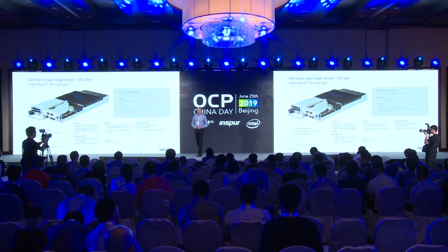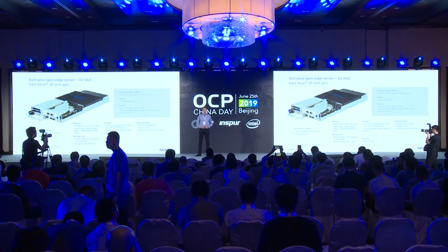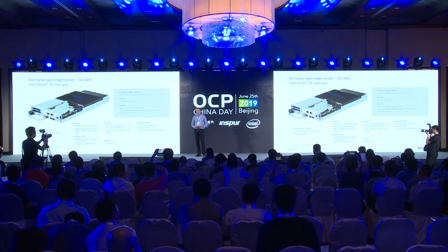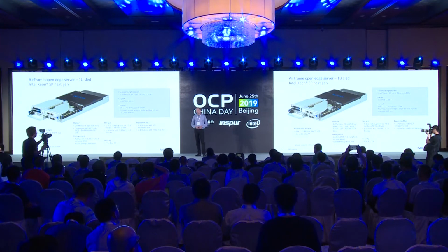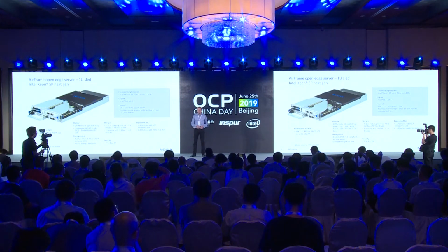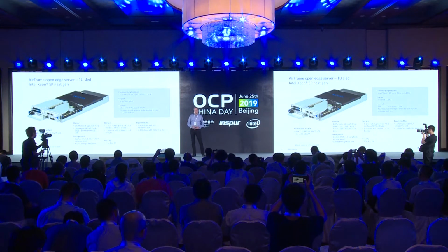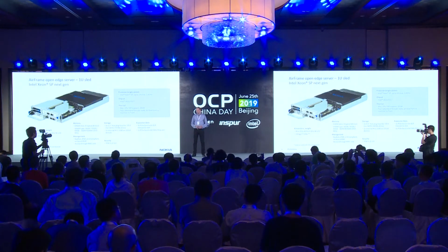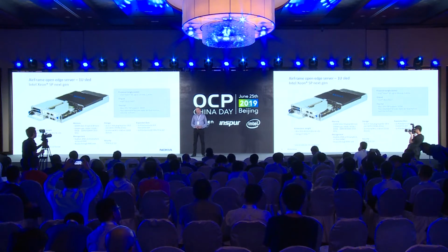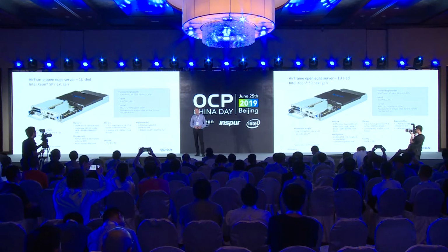So this is a picture of the 1U sled. It's Intel Xeon SP Cascade Lake based. And we are supporting up to 24 cores at 2.5 gigahertz. And the TDP for the CPU is 205 watts. And both chipset types, PCH, are supported: C621, the basic solution, and then the C628 for the QuickAssist functions when those are needed.